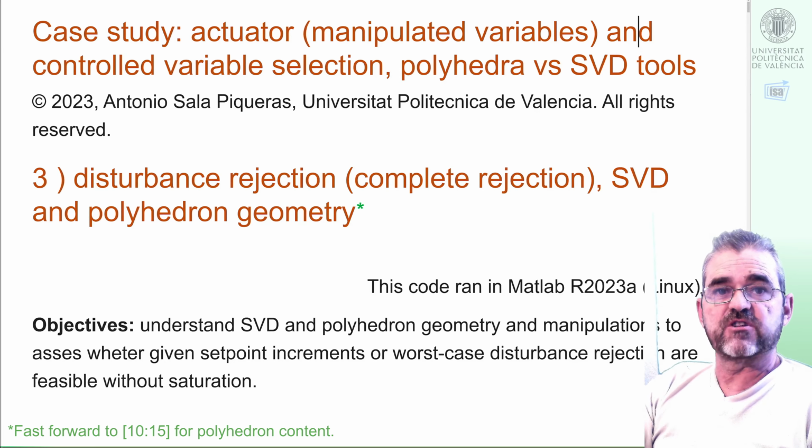But well, if we keep that output scaling, then this will be the gain of G and the disturbance effect scaled to the same output units when subject to scaled input variables, in this case scaled disturbances. Well, then H scaled will be this H gain.